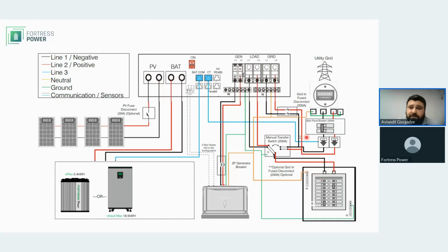Power comes from the grid, travels through the inverter, comes out of the inverter load ports, and goes to the main electrical panel. And your batteries are there to reduce the import. Your PV is there to reduce the import. Perhaps if you have enough power, even export something to the grid.